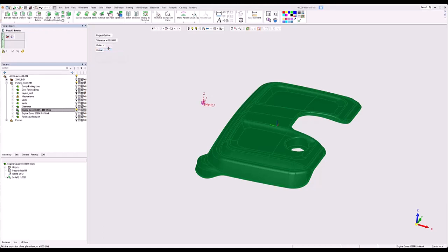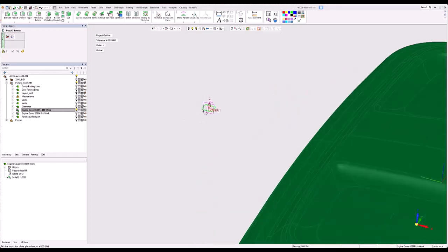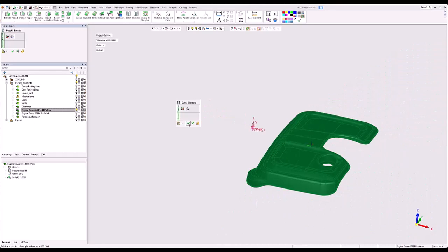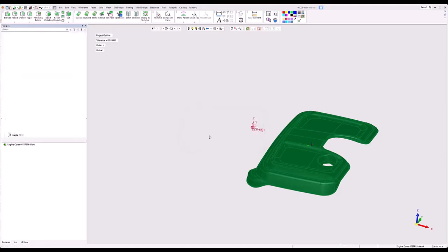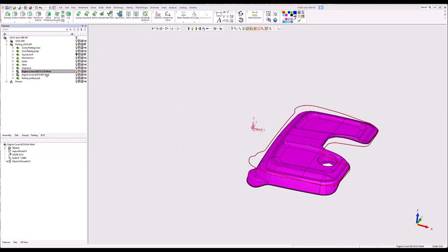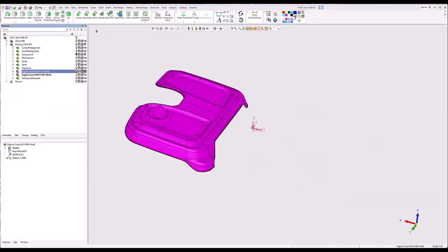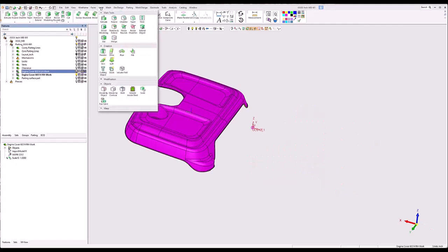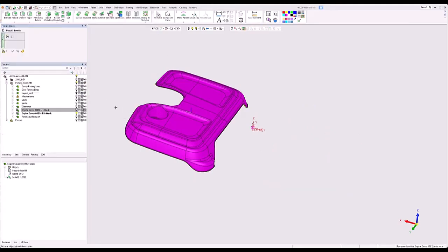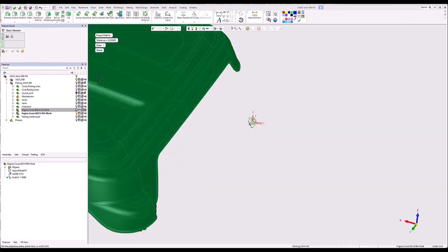I just want the outer edge, and now I'm going by project, and I'm going to pick a plane or a planar face. It'll always come up with a looser tolerance message. I think 10 thou's loose enough and accurate enough for what we're going to use it for. I'll do the same thing to the right hand part. Make sure I pick outer, pick a plane or a planar face.